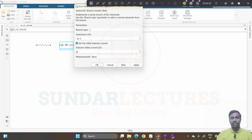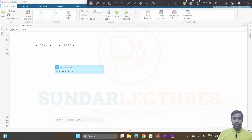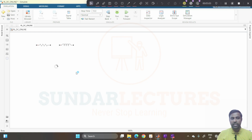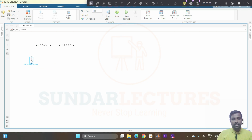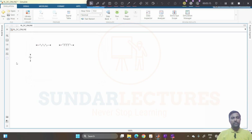Maybe you set the initial current to be 0 and you can close this one. Now what we need to do is take a DC voltage source. You just type it out, you can see a DC voltage source here. Click this, and you get this one here. So this value here, make it 10, that is up to you, no problem. 10 volt, right?